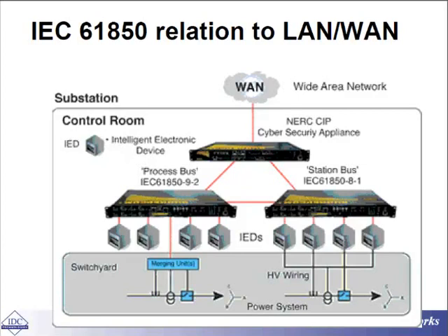The idea is to use a number of IEDs, which are multifunction, and I'm not saying exactly what they are. Is that a microcontroller or, I don't know, a protection relay or what? I'm just calling them IEDs, and I'm just going to interrelate these IEDs by means of a number of IEC 61850 protocols and, let's say, gateways.